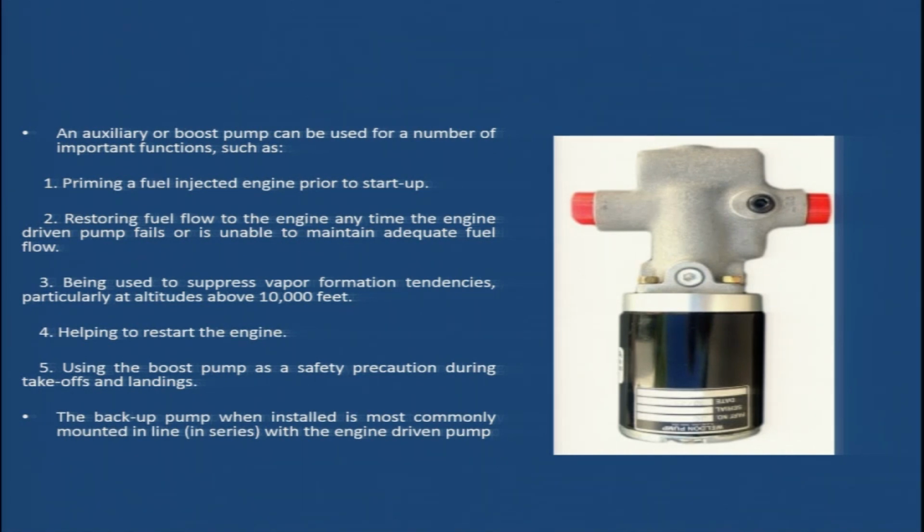In case we are required to restart the engine, this electric fuel pump is helpful. Using the boost pump as a safety precaution during takeoffs and landings. During takeoffs and landings, it is a mandatory requirement to have the booster pump on, the electrical fuel pump on. This is an extra safety precaution taken during the takeoffs and landings, so that we have fuel supply from two pumps.